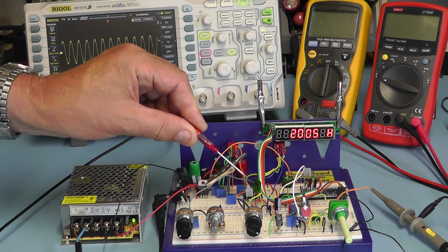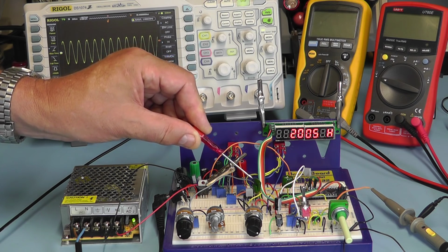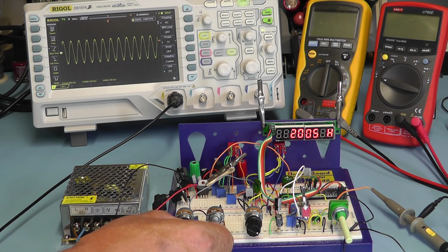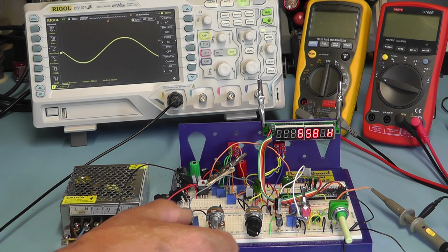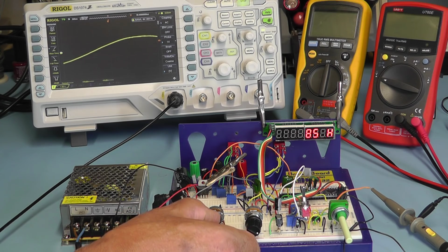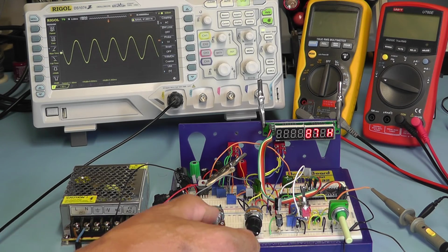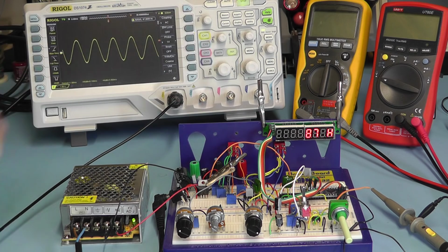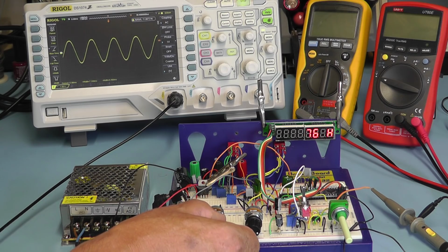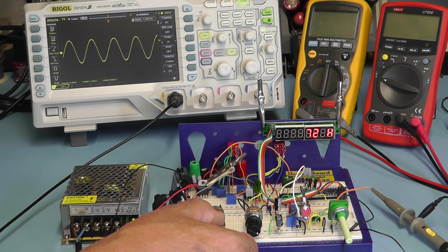Here you can see I have the frequency set by having 2 capacitors there in parallel for the moment, so that's setting now the lower frequency range. So let's just see what the range of that is. If I take the controls to the minimum frequency, there we're getting a frequency of around about 87 Hertz at the moment. Sorry, I'm getting down to, well, 72, 71 Hertz is the lowest frequency.